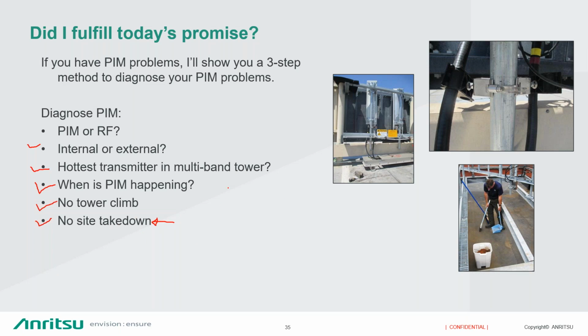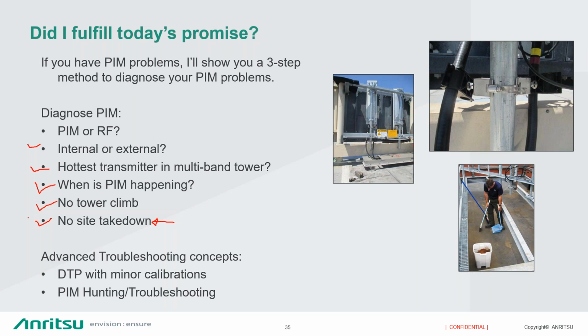And if you do have access to the antenna and you do have access to doing a roof climb, you can do a full distance to PIM calibration so that you can do a distance to PIM analysis. And then I went over some PIM hunting and troubleshooting scenarios that, again, does require a second webinar. And let me know if you guys are interested in a webinar on some of the PIM hunting, where I combine using data from the IQ FiberMaster with the PIM Master to do a full-blown external PIM analysis and internal PIM analysis if that's where your PIM is.